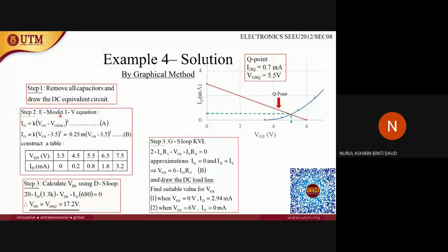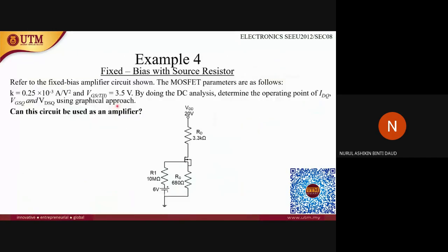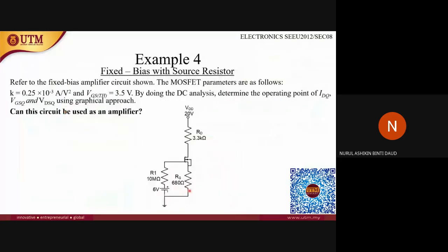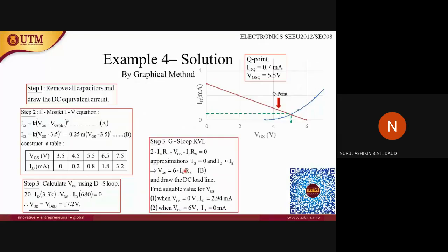And then step 2. But in the exam the circuit is sometimes going to be very complicated. So when you see all those complicated circuits, don't get dizzy, don't panic. What you have to do is just remove all the capacitors and draw the circuit. It will be like this, right? So that is always the first step.